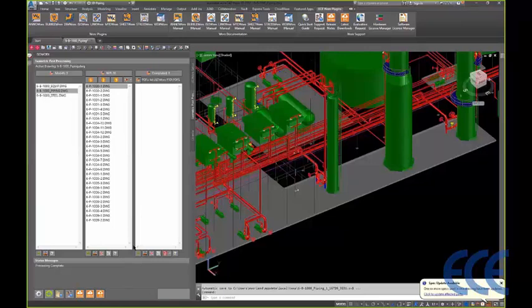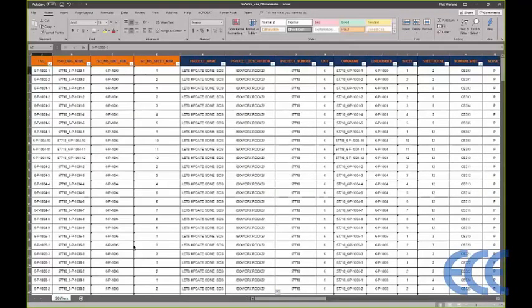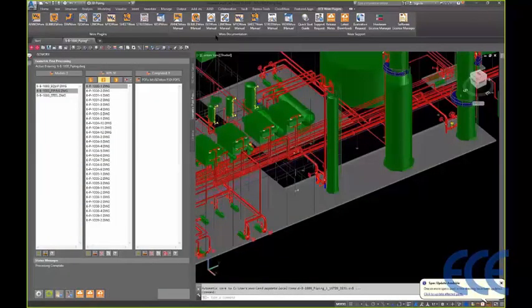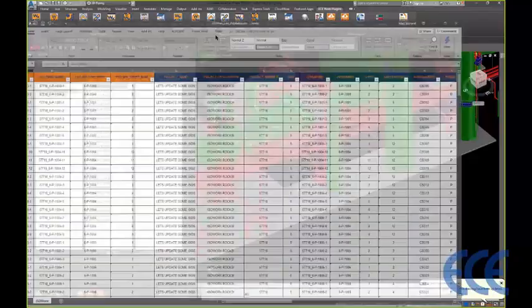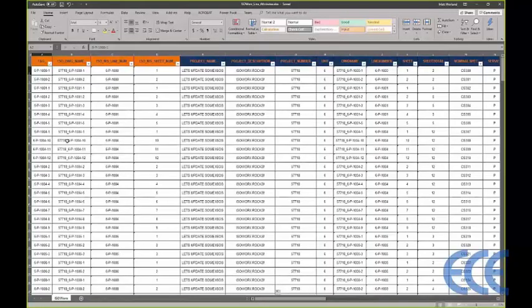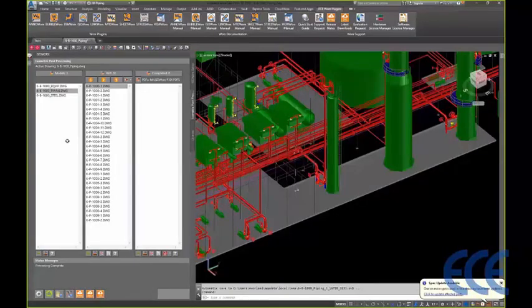Now onto the post-processing side of things. We do give you 3 options. So the first option here is number 1. It will allow you to take this line number and append the information that you found in this DWG column. So in the end, the ISO name will look pretty much like this. So 6P dash, and then have this information. The next option, number 2, is just we're going to take this name and get rid of it and only use the DWG name. So whatever's in this column, we're going to completely rename the ISO to that format.